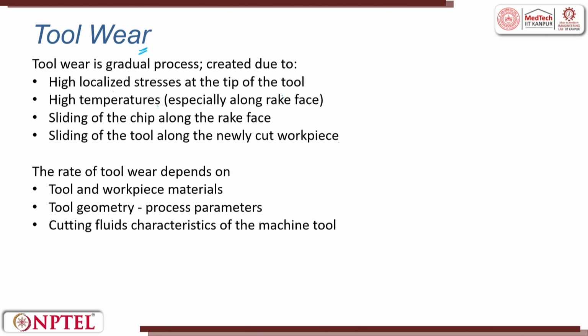All these things lead to tool wear. The rate of tool wear depends upon tool and workpiece material, tool geometry, process parameters, and the cutting fluid we use. So, these are the measures which we take to reduce the tool wear.